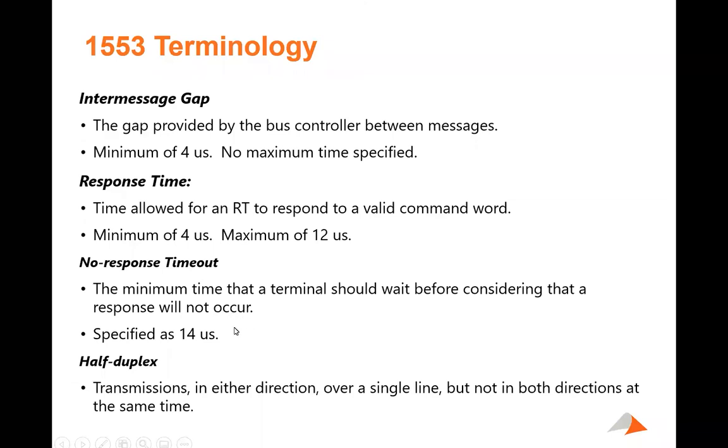All right, so if a message goes out and the response doesn't come back, that timeout occurs at the 14 microsecond. That's why you have 14 microseconds for that first part of your RT's response to come back to the bus controller, or it will declare it a timeout, and it gets messy sometimes after that.